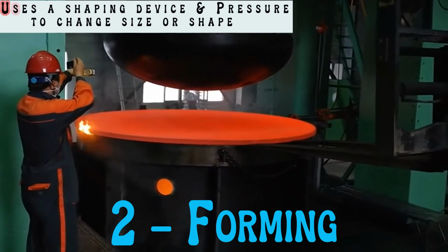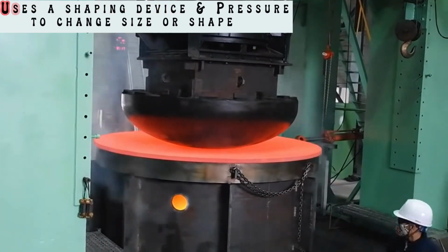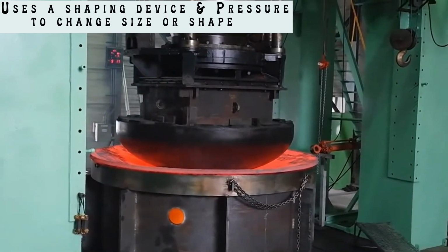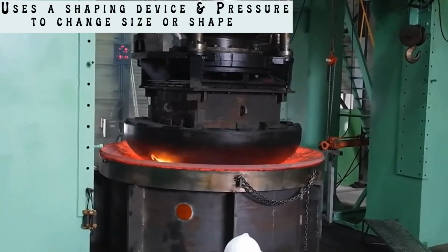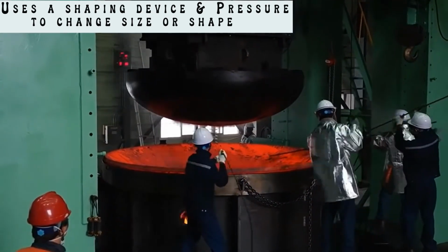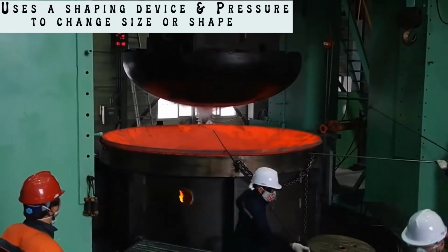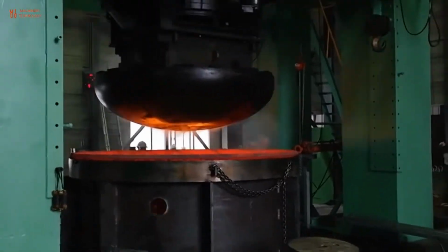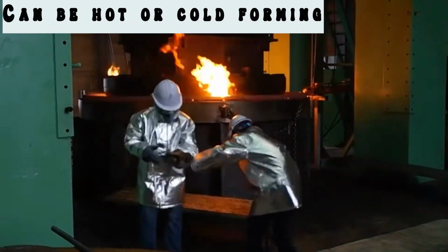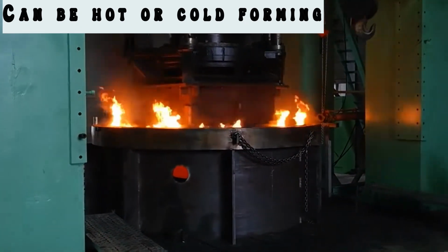The other way of processing materials is by forming. Forming uses a shaping device and pressure to change the shape or size of a material. Forming operations do not change the weight or volume of a material, but it does account for temperature. It can either be done at high temperatures, also known as hot forming, or at room temperatures, also known as cold forming.